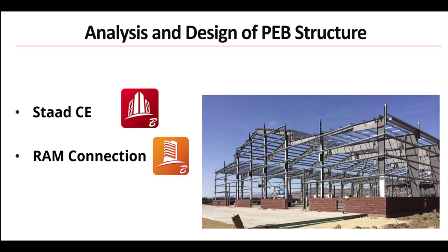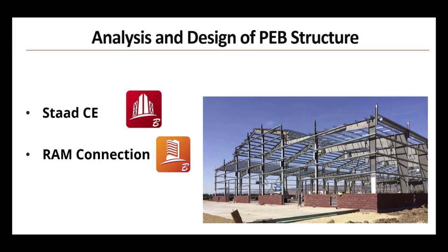The products that we are taking for this entire modeling are basically STAAD Connect Edition, and then some portion of the connection designed by RAM Connection software. We will model, apply the load, assign various support conditions and sectional properties, analyze them, and then perform the member design in STAAD.Pro. Then we'll export a few of the connections to RAM Connection and design them.